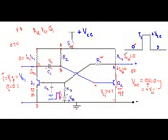And in the output you will see that whatever the condition of the circuit, our output will again come from VCC to 0 volt, because it is the only stable state for this circuit. Only stable state means the output voltage will retain its value at 0 volt whatever the condition of the circuit. As 0 volt is its stable state, between 0 and 1 only one of the states is stable. That is why it is known as monostable multivibrator. And you will see that for the transition from one level to another, I have applied only a single triggering pulse. That's why it is known as one shot multivibrator.